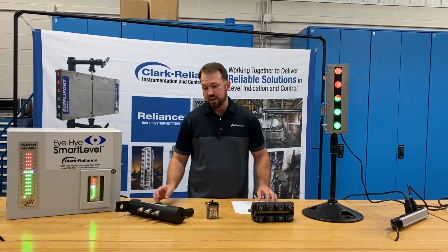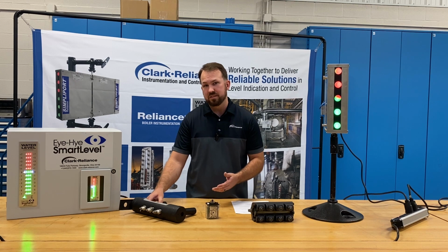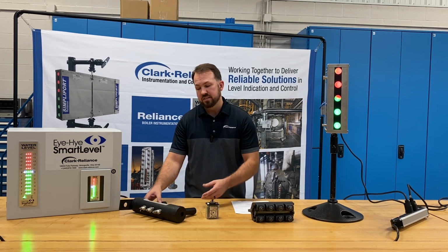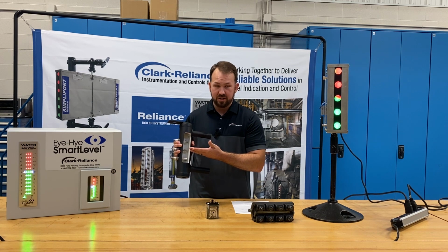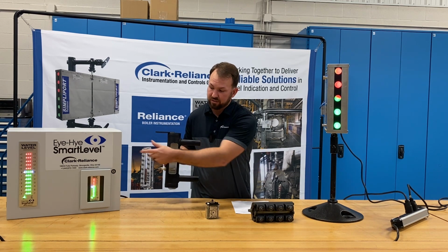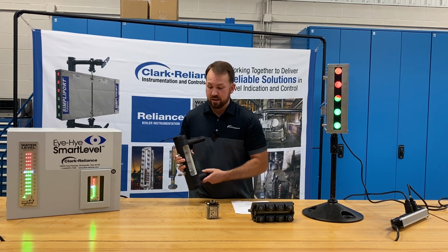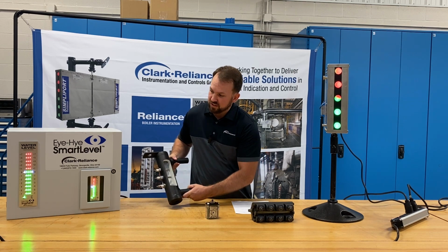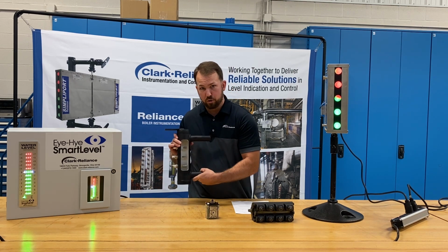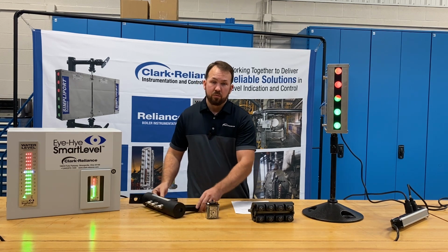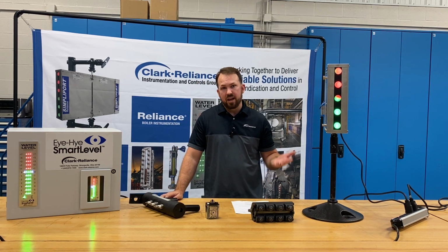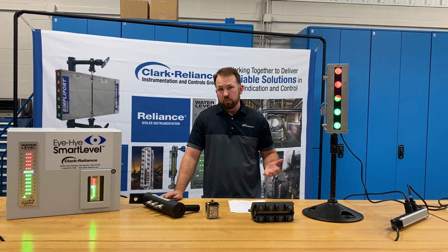A remote level indicator, on the other hand, you cannot physically see the water level in the gauge. This is a device that uses some type of technology to transmit what water level is inside this device to a remote level indicator, as the name implies. Examples of this include our smart level system, which is going to have the control unit and a probe column like I'm holding here, a magnetic level indicator, where it's using a float and a series of flags to show where the level is, guided wave radar, or another option is differential pressure transmitters.